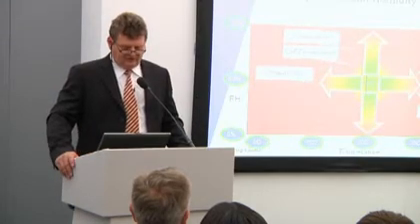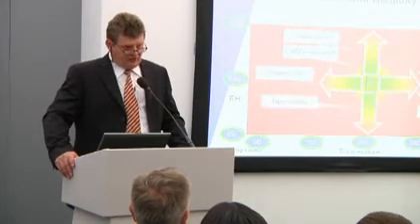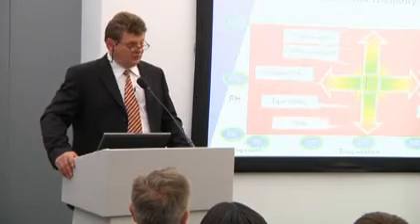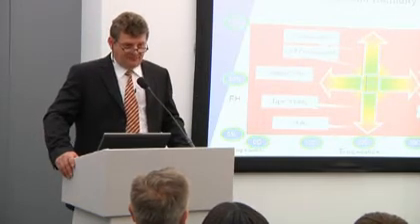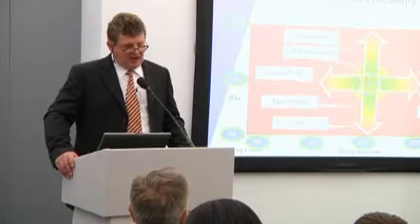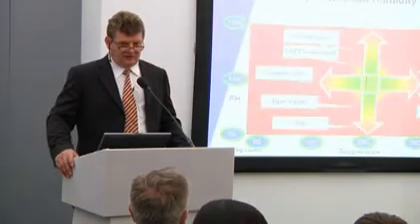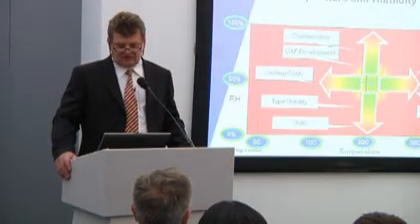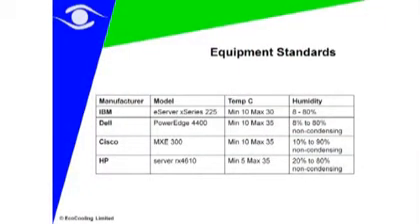Low humidities are associated with tape stability, the old paper tapes and paper card systems. And also low humidities have been associated with a thing called ESD, electrostatic discharge. So people in the data center and server and IT world appreciate these factors exist, but many people don't understand where the modern lines are drawn.